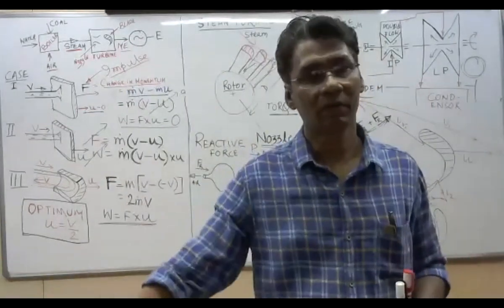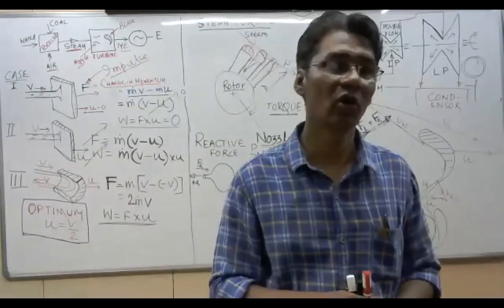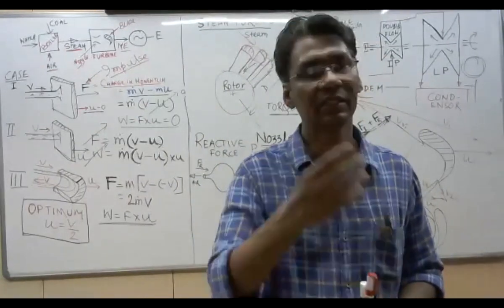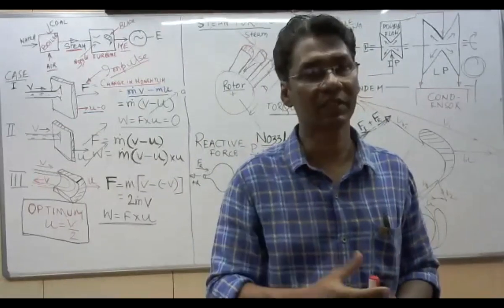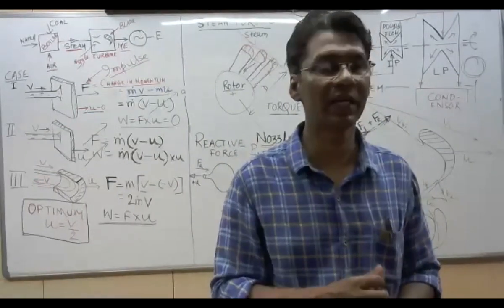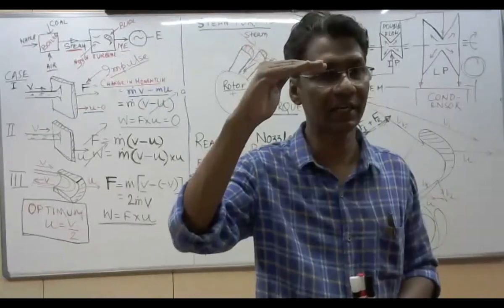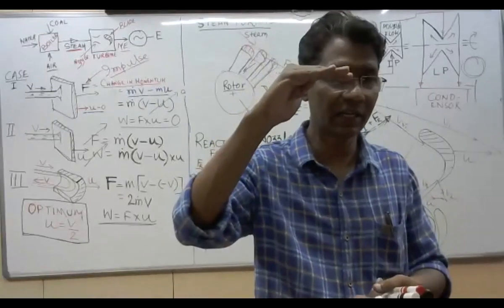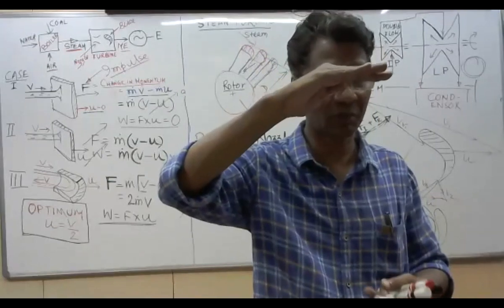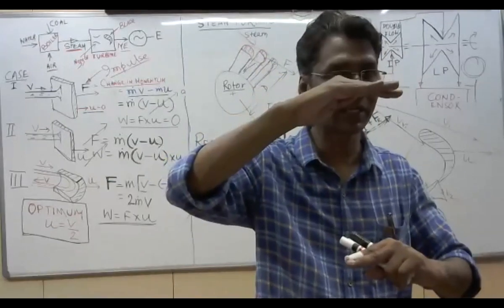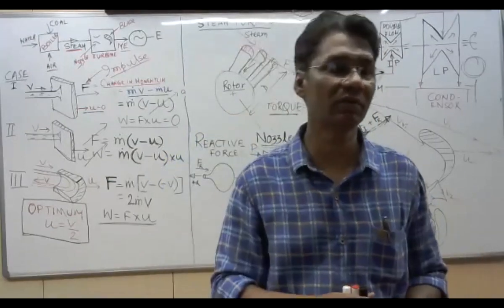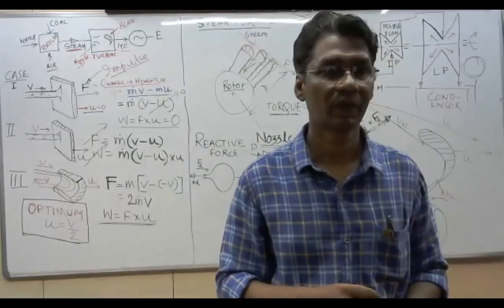At the condenser, the vacuum is below atmospheric pressure, that is below 1 kg pressure. Condenser pressure is 0.1 kg, that is below atmospheric pressure. Atmospheric pressure is 1 kg standard, so 0.1 kg is the condenser pressure. That is the last stage pressure of the steam turbine.